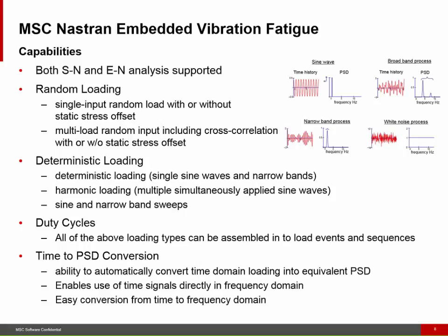You can have deterministic loading, which may be a single or multiple sine waves. It can be narrow band, or it can be sweeps of those. And all of those types of loadings can be assembled into load events and sequences to make up a realistic duty cycle.